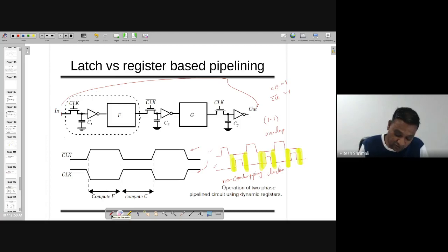But let's assume that you are using only this particular transistor. The reason is the input might be 1 or 0, anything it will be. So an NMOS can transfer 0 strongly to the other side. However, for 1 there is a drop of VTN, as already known, and if you are using PMOS, it can transfer 1, but it does not transfer 0 efficiently.